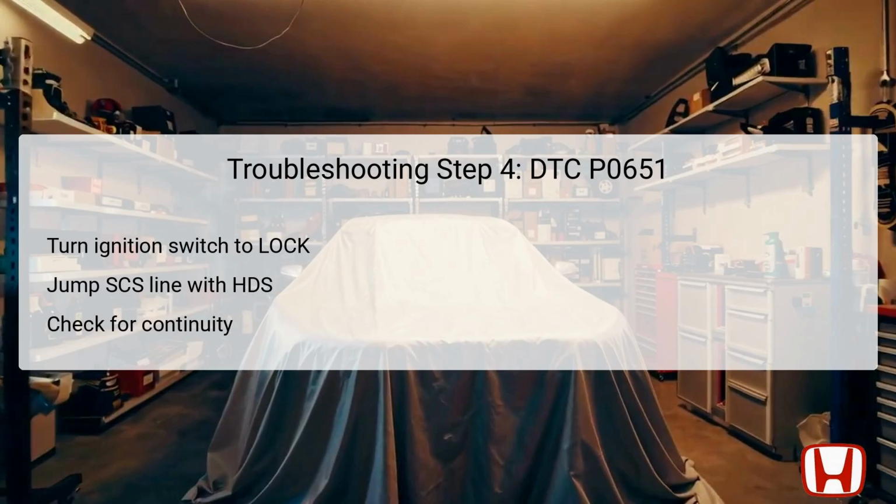If continuity is found, this suggests a short in the VCC wire, necessitating repairs between the ECM and the affected disconnected parts. If no continuity exists, the next course of action involves determining if an ECM software update is needed or considering substituting the ECM with a known good module.